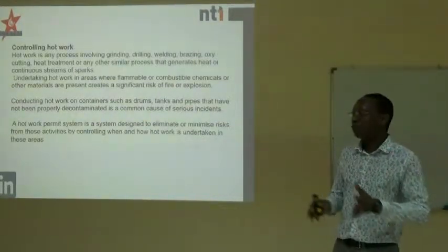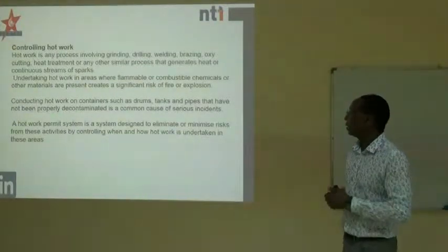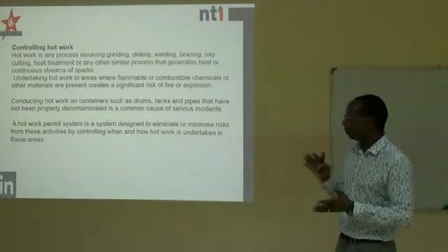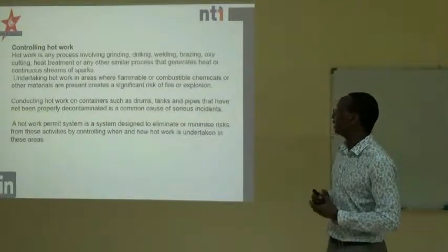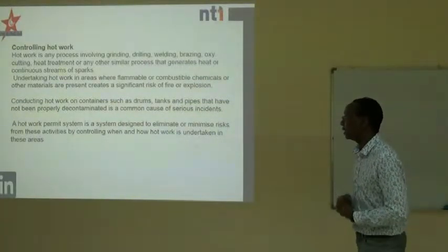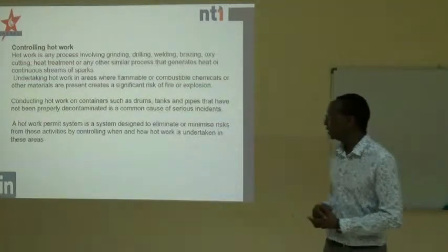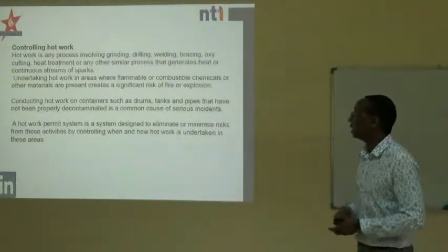All over the world, people have died because of that. With hot work, it is very important for you to make sure that the place you are working at has been properly decontaminated. So the hot work permit system is a very important thing. It's a system designed to eliminate or minimize risks from these activities by controlling when and how hot work is undertaken in these areas.